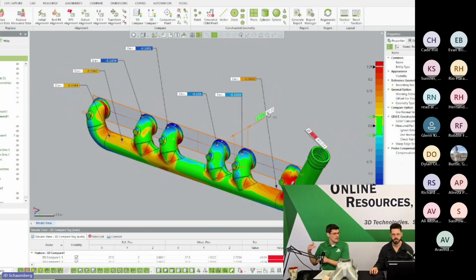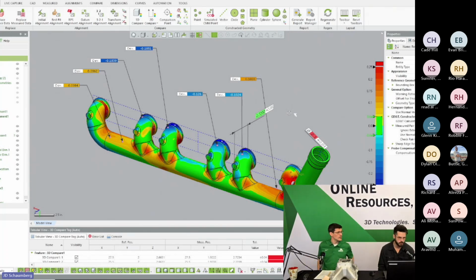It's a user defined tolerance. Like let's say we have a surface profile tolerance of 60 thousandths. I would adjust that to plus or minus 30 thousandths. Okay. And that would be your overall surface profile of the part. So this is really where, if you just need to know roughly, do you have enough stock? A color map could say that for you. Yes, correct.